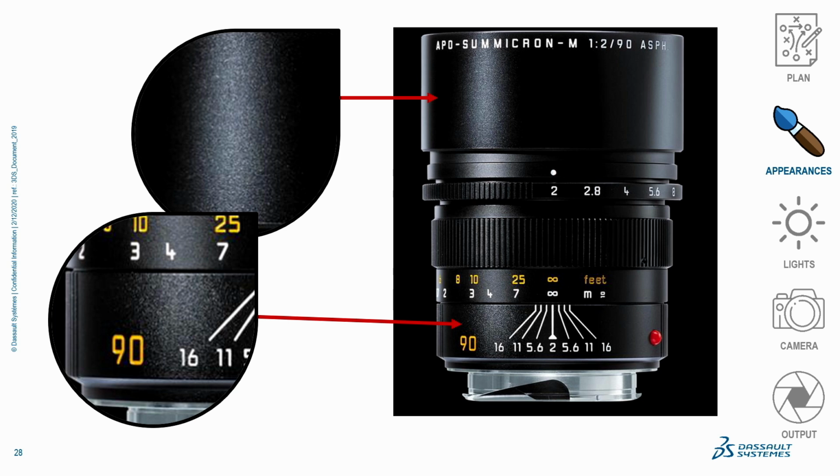So this piece on the bottom is metal, this piece on the top is plastic. So they're both black, but they're a different shade of black for sure. It's probably hard to see that on the projector, but when you're looking at your reference images, you can pick up those kinds of things, right? So this is a case where I would use my SolidWorks filtering to set up an opportunity where I can switch those pretty easily, because if I apply the same appearance to those in SolidWorks, then especially if I'm using appearance grouping, things get all crunched together and then I've got to try to separate things out.